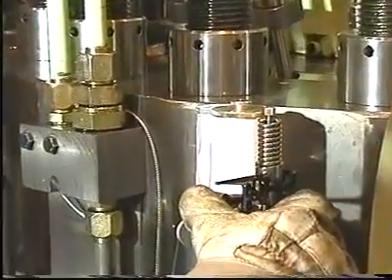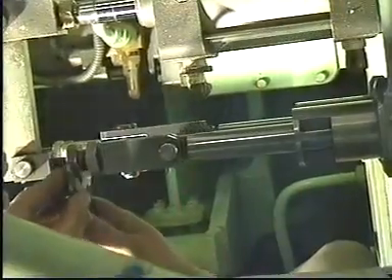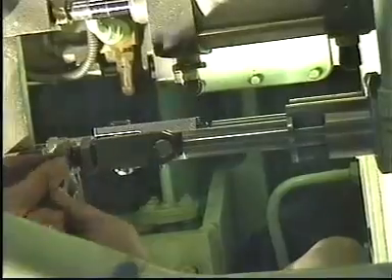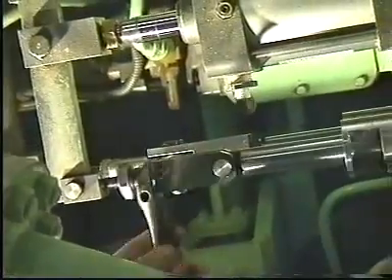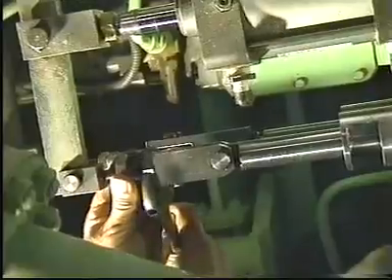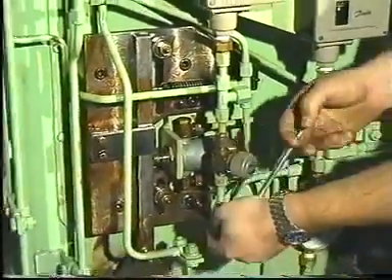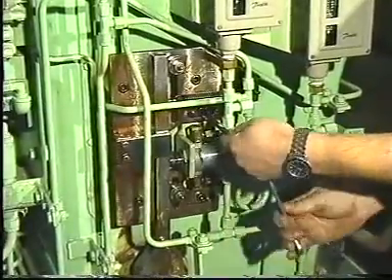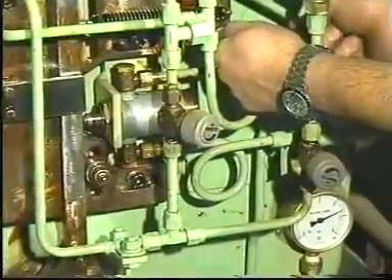Measure the maximum combustion pressures regularly, especially after bunkering new fuel oil. Adjust the individual links until the maximum combustion pressures, corrected to ISO ambient conditions, are uniform and have the required value. If all the maximum combustion pressures are either too high or too low, displace the pilot valve bracket.